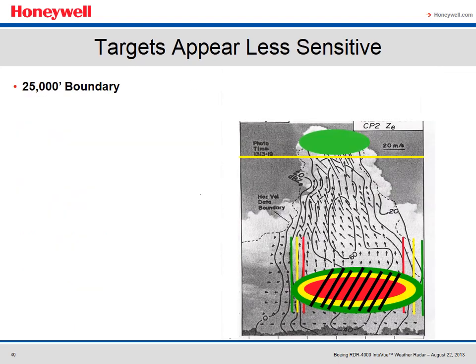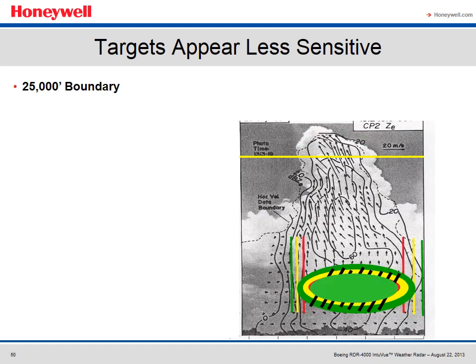And for the same reason, it might appear at times the system isn't sensitive enough. In this case, the height of the cell has been decreased, so the pilot only sees green above 25,000 feet. But remember, the flight path weather always has priority over and covers the secondary weather. So the flight path weather, which is green, covers the yellow and red at the lower altitude. But again, use the key. Think about altitude first, then color. The system is telling the pilot this cell has moisture above 25,000 feet, has entered your protection zone, and should be monitored. So how do you make your deviation decision?